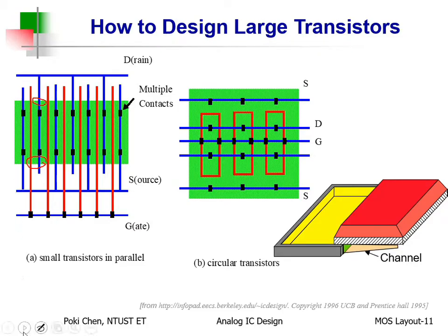In this way, stacked layout helps us to reduce the parasitic, especially parasitic capacitance. Okay? If you have a look at this one or that one, you have three side walls, just like this, and that, right? With large parasitic capacitance. But the inner one has much less parasitics. That's it. Okay? Got it? Alright.